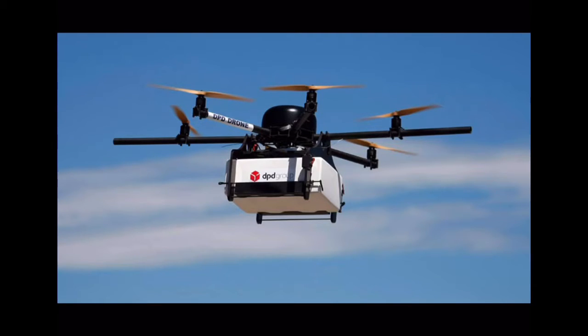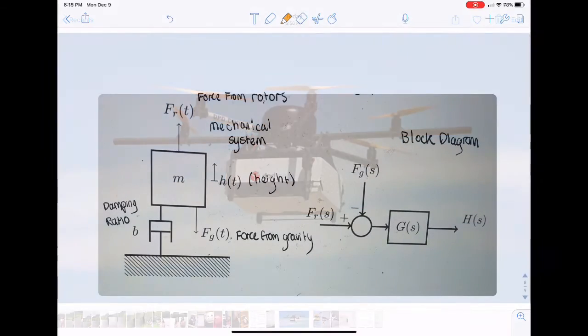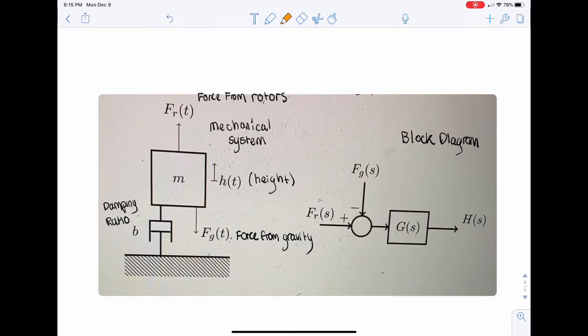As the technologies of UAV continue to develop, control engineering has the capability to demonstrate better performance by identifying current problems and finding a technological solution. Our goal is to safely maintain the quadcopter at a constant height, which in turn will allow for the safe delivery of packages. In order to do this, the upward force produced by the four motors will be the variable controlled, and the height of the plant will be the output variable.